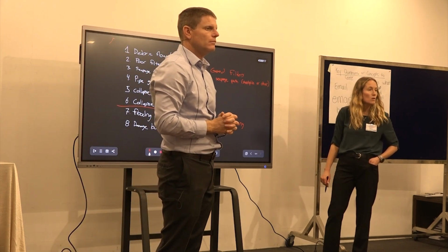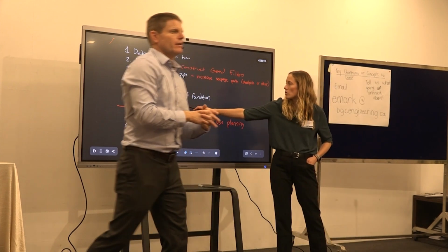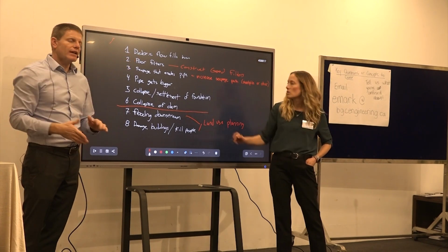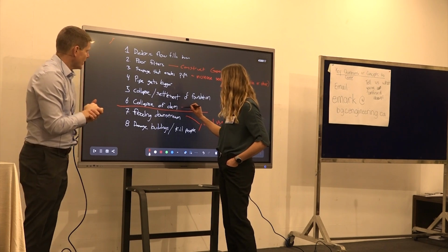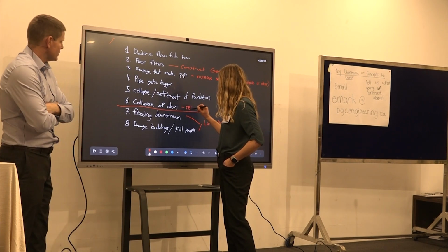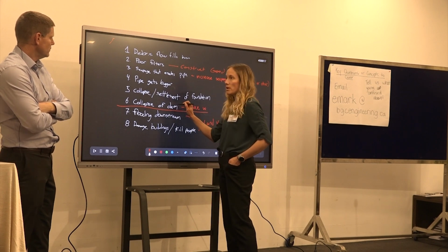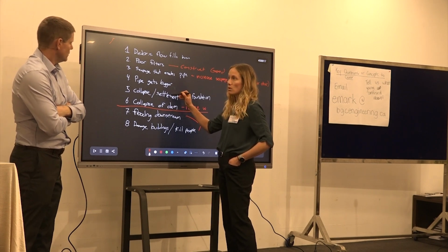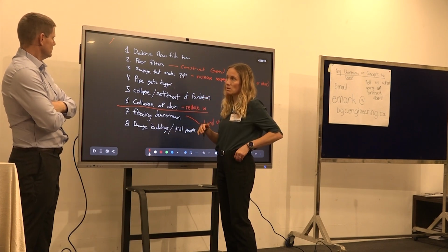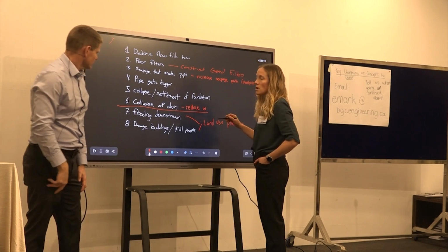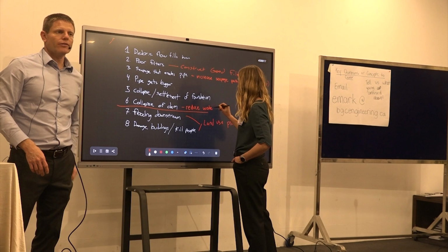So I'm saying that we should decrease the water level of the dam. Yes, water level, by having a spillway, I think. Yes, that's right. So we can adjust the height of the spillway to limit again the gradient of the seepage. If you start building the pool, if the collapse starts, the water level's been drawn down, then maybe it decreases the likelihood of it. Okay. Yeah. Other ones? Anyone else?